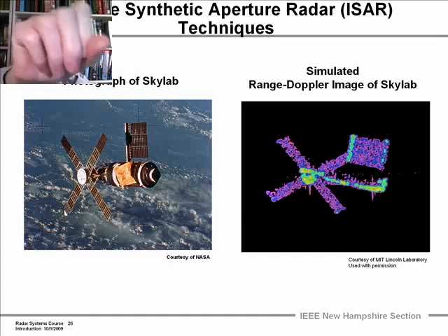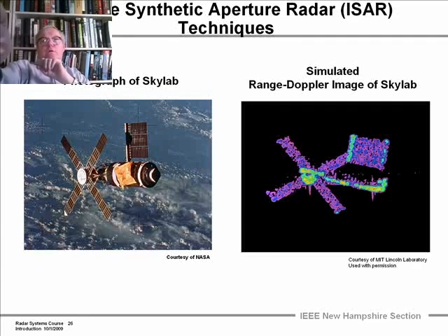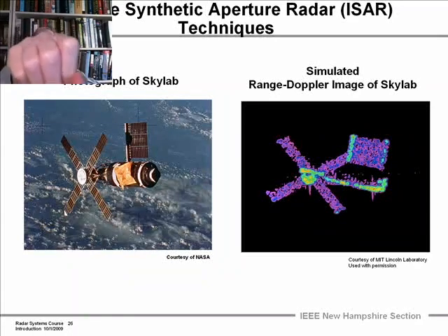Now, when the radar and both ends of the dumbbell are along the same line of sight, there's going to be no radial velocity of either of those objects. But as they move, one will have a positive Doppler and the other will have a negative Doppler. And so if my hand right here is at 0 Doppler, what you'll see in successive Doppler processings of different bunches of pulses is you'll see at the center a big bump from both of them, and then they'll move away and they'll move here.